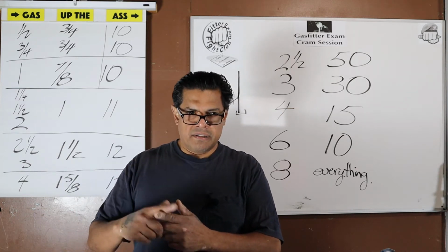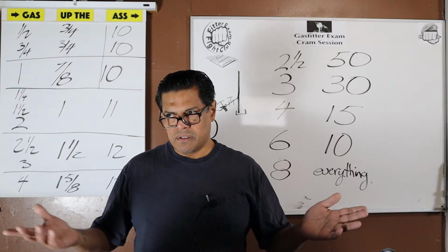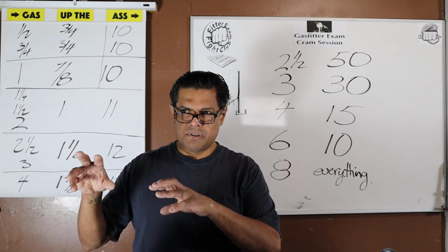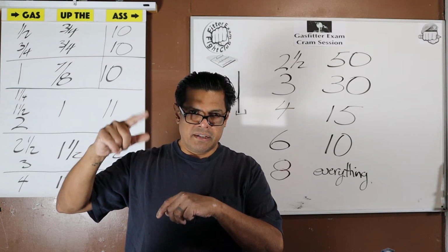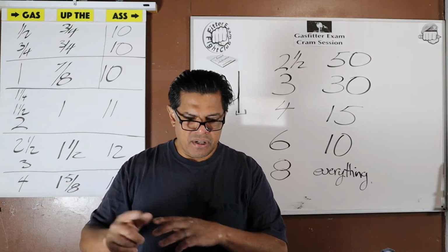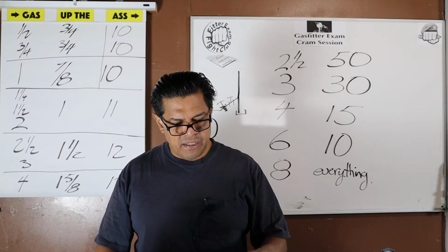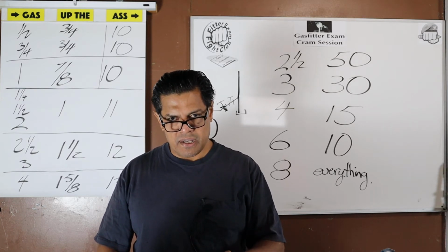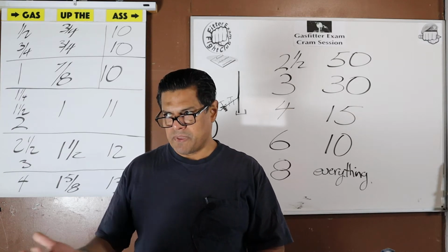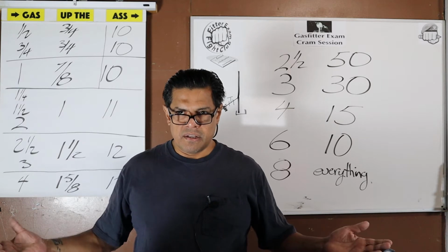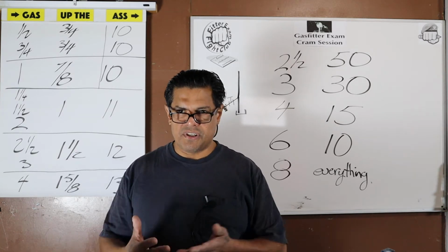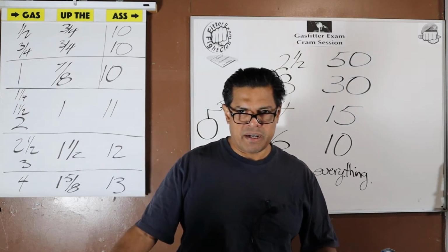The test T. Test T is for testing. So usually it sits there when there's no test. It's plugged. The outlet of the T is plugged. That size is 1/2 inch. Since you have to have at least a 3/4 inch line to a range, that 1/2 inch line discourages an unwanted connection to a stove, since the stove's just not going to work. 1/2 inch is just not going to supply the amount of gas you need for that.